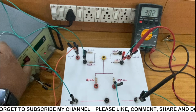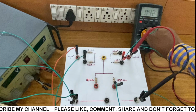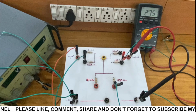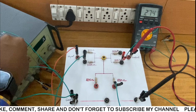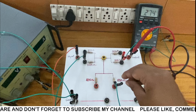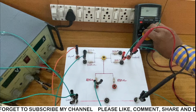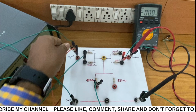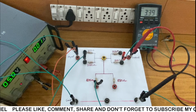Now for the resistance we are going to remove the supply. We are going to short the R1 with R3, and then the resistance measurement is showing us 0.274 kilo ohm, or we can say 0.275 kilo ohm. So it is 274 ohm or 275 ohm. For the next iteration, we are going to connect the resistance to 470. We are going to select DC voltage, remove the short, connect it to the input, make the circuit on, power supply on. We are getting 3.39 DC volt.